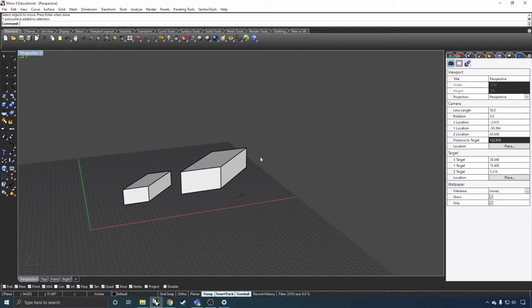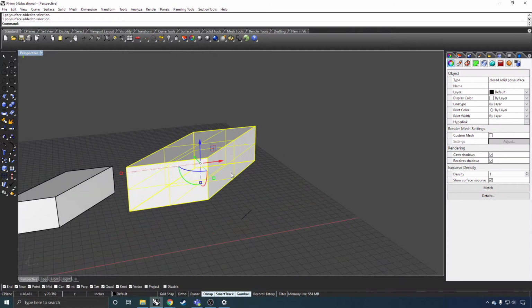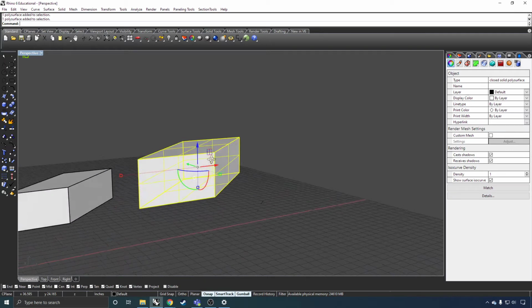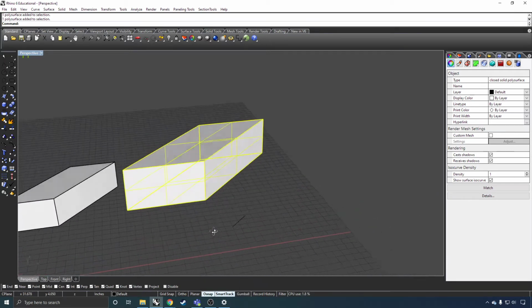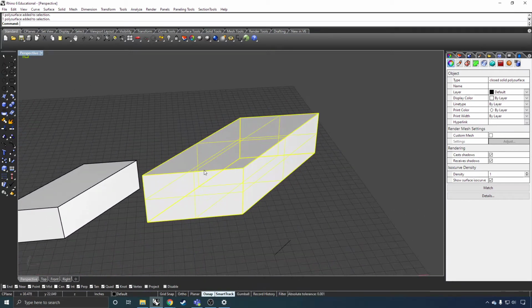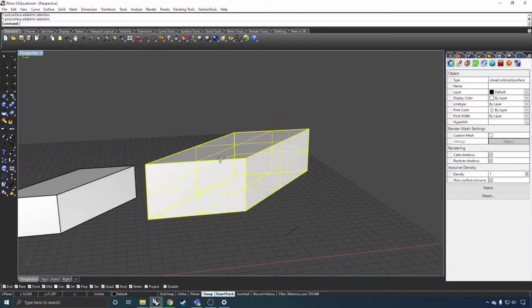But generally, what we're using are vectors and NURBs and other mathematically defined surfaces. So if I select this object, you'll see that it has 6 sides, and we'll turn Gumball off here just because it's a little bit easier to see for a second. It has these lines coming through the middle when I select it, that are defining the surfaces mathematically. But generally pretty flat. This would be pretty easy to represent with polygons, but you would probably see a triangle coming around the diagonal here.